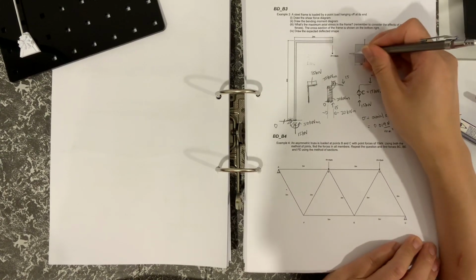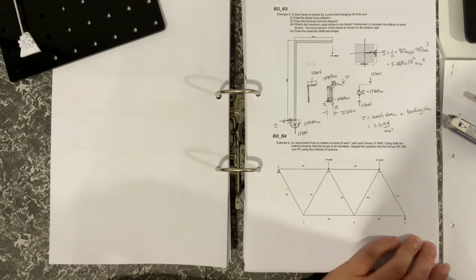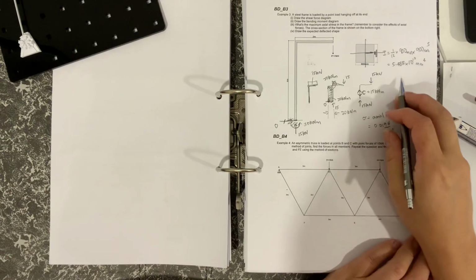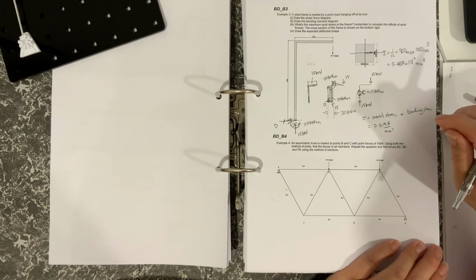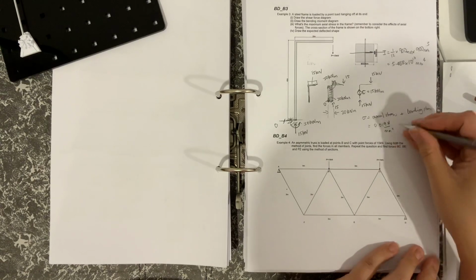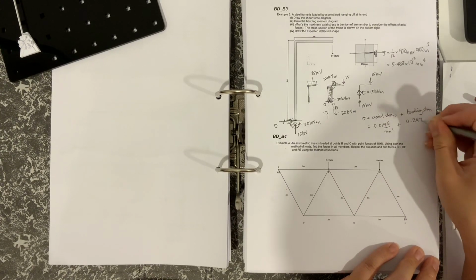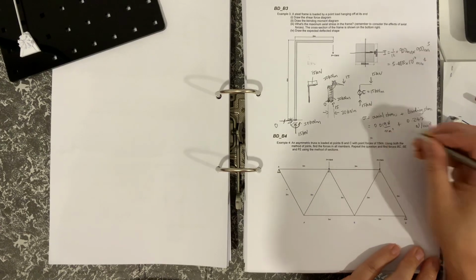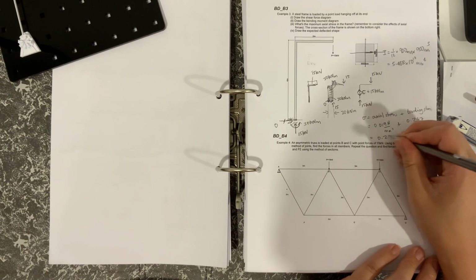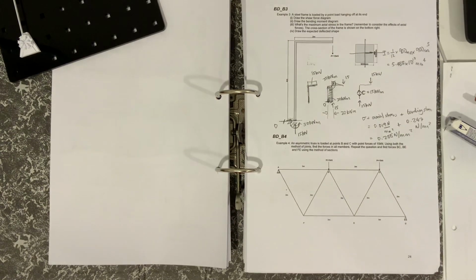The distance y this time, since it's like that, would be that distance there, which would be 450 millimeters, and then you divide that by I, which you've already calculated, and so you'll get the two stresses which can be added together. The bending stress would turn out to be 0.247 newtons per millimeter squared, and then the maximum stress would be the sum of those two, which would be 0.266 newtons per millimeter squared. And as I said,